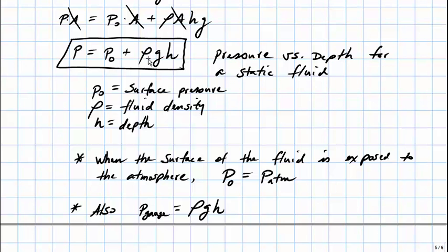If we look at this equation, if P0 is atmospheric pressure, then rho g H is the amount in excess of P0. Therefore, rho g H is the gauge pressure. Under these conditions, this equation can be written as follows. And we will note that this last term equals P gauge.